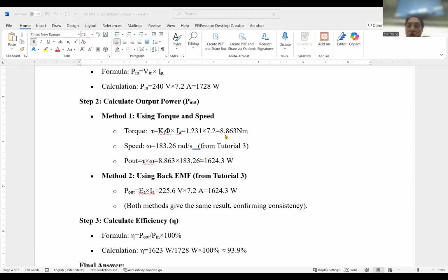So if you want to change the IB, one thing we can do with the IB equation is, RA is fixed, but the second one, RB, you can change it. So I think I also asked you before, what kind of braking resistor is the best? Is it a large RB or a small RB to brake the vehicle or brake the motor?